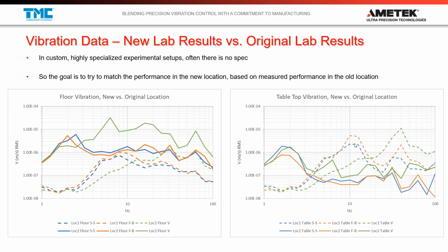were known to have a low frequency problem, being on passive isolators, because of the resonance of the isolators, even on the quiet basement floor. So they already deflated these isolators, which is why you don't see a resonance peak here for the tables in the original location. But you do see resonances around these frequencies, which is probably close to the resonant frequency of a deflated table. And then here you have location 2, the table.